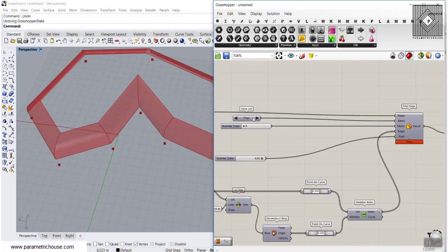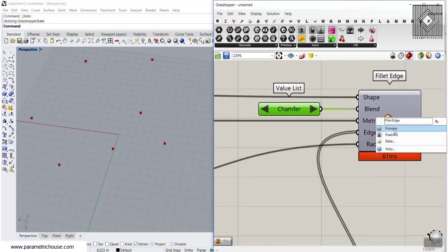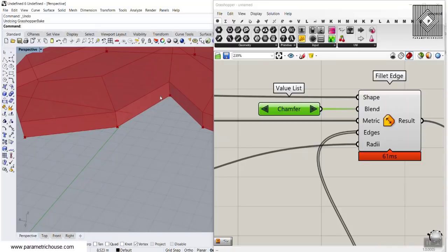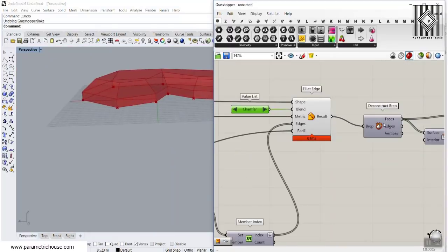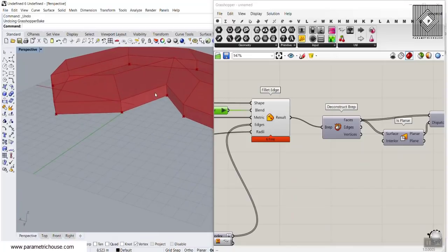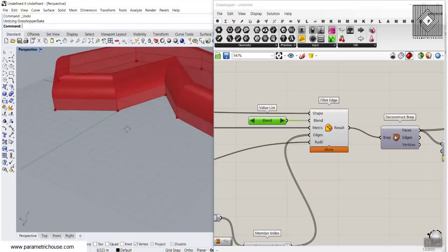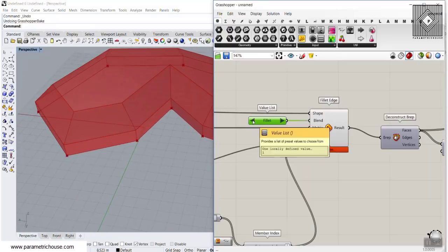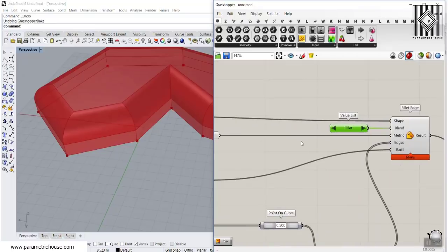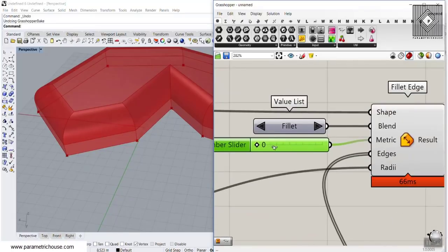And you can also change that fillet to chamfer, but remember, if you just put that as a chamfer, this will be just flat, so you can't use this technique. To do that, you have to go for another way. That's perhaps going for the direction of the vectors. So then you can also go for blend, and you can see that this is giving you 2 or 3 different results. The next one is the metric, so I'm going to change the rolling ball into edge.